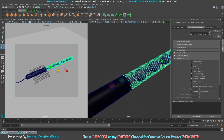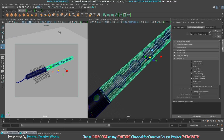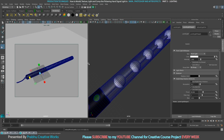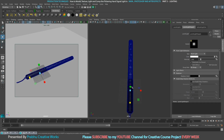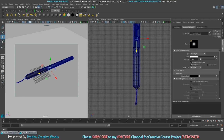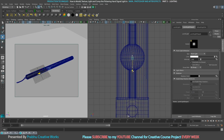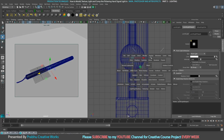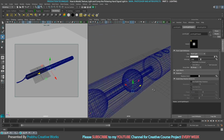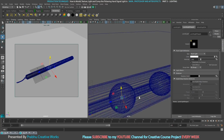So now we want to set LED effects to this inner part. So go to rendering and click on point light. So press W and then move exactly in center. So go to top view, press 4 to see the wireframe. You want to place the point light exactly in center of the sphere. Go to perspective and move upside like this.